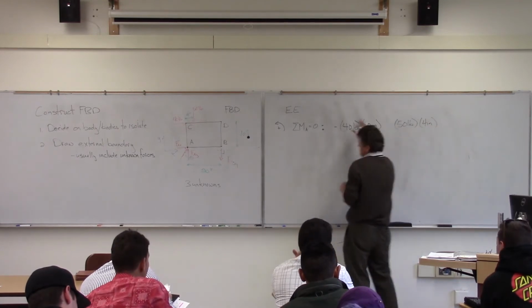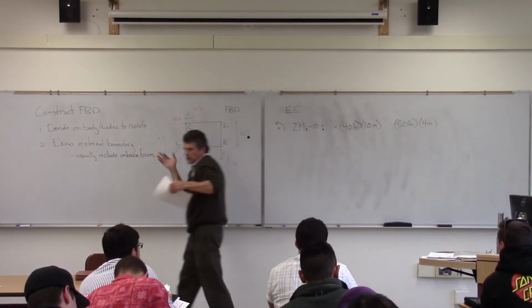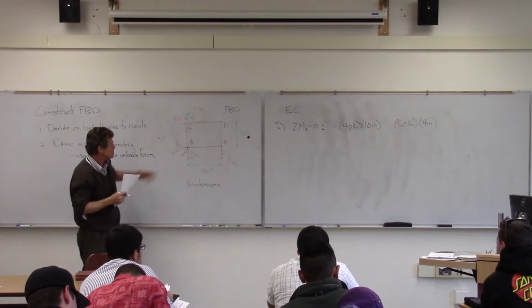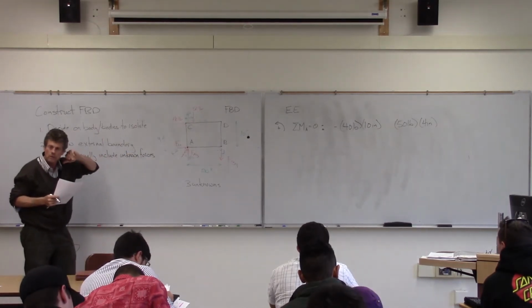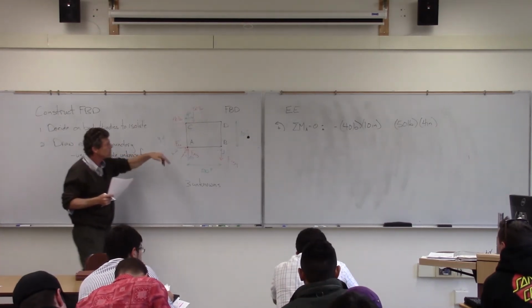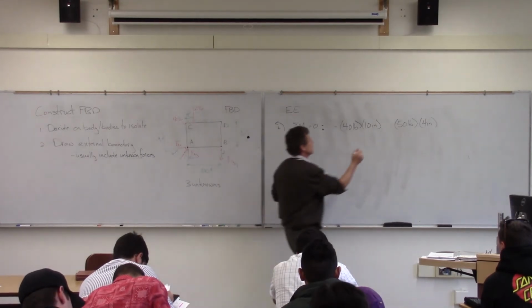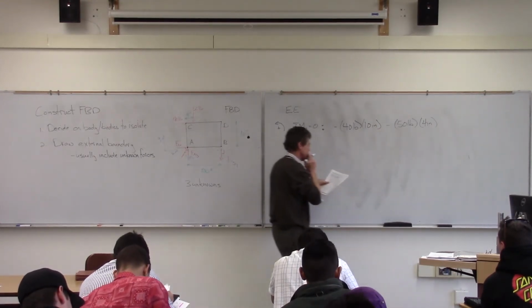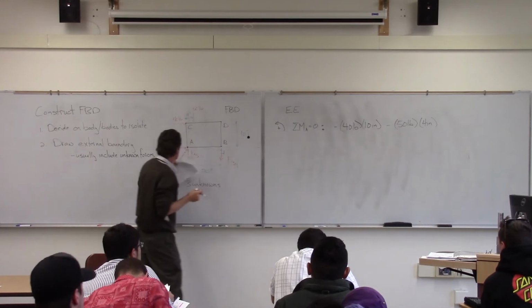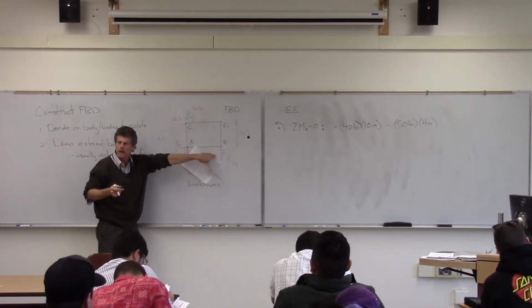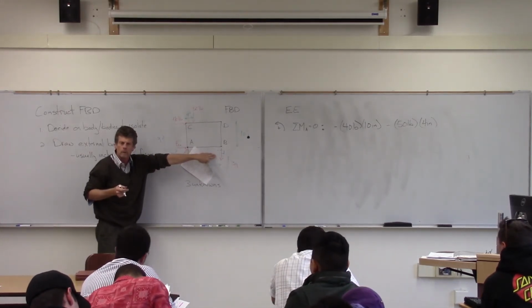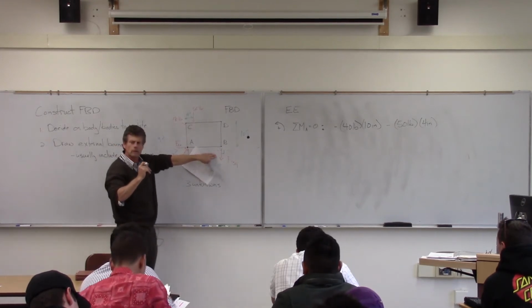Now again, note that these moment arms are very simple. They're all going to be those perpendicular distances, since I've broken my forces into x and y components there. And again, it'll have a negative sign. And then the only other force that will contribute there is my FBy, the one that the young gentleman said, boy, that just doesn't look right.